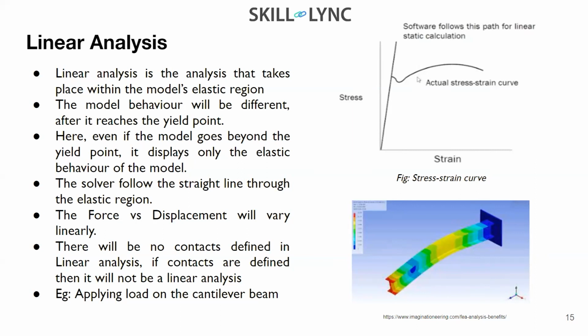Okay, so what is the thing we are trying to study in linear analysis? Like you can see a cantilever over here. In linear analysis, there is no point in having a contact. What I mean by contact is, suppose there are two bodies touching each other. That contact study will not be useful in the case of linear analysis.